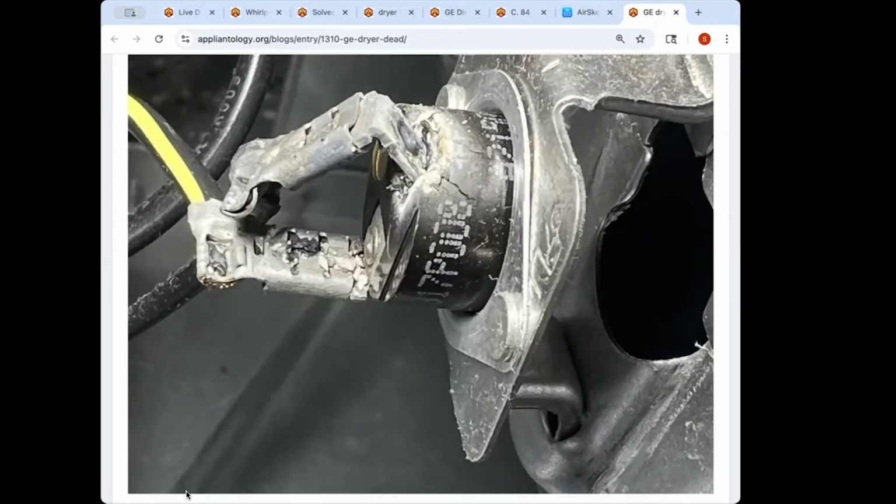And Tim, that's an interesting point you made with the gauge of the wire, and they went to a larger gauge. Wire has a certain ampacity, in other words, the ability to carry amps safely. If the diameter of the wire is too small, the gauge number actually goes up. But if that diameter is too small for the amps it's supposed to carry, that wire will start generating heat, and you start doing things like melting conductors in extreme cases, or just creating heat at the connections.